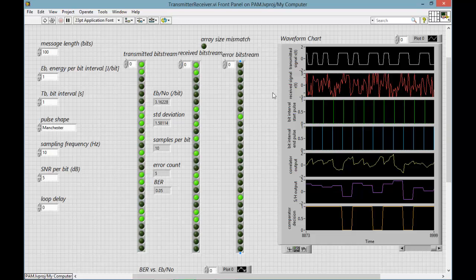We can also see at the same time that the received signal is not very intelligible to the eye, even though the system has done a pretty good job of regenerating the input bit stream. So coherent detection excels in regenerating the input bit stream even if its SNR is pretty low.